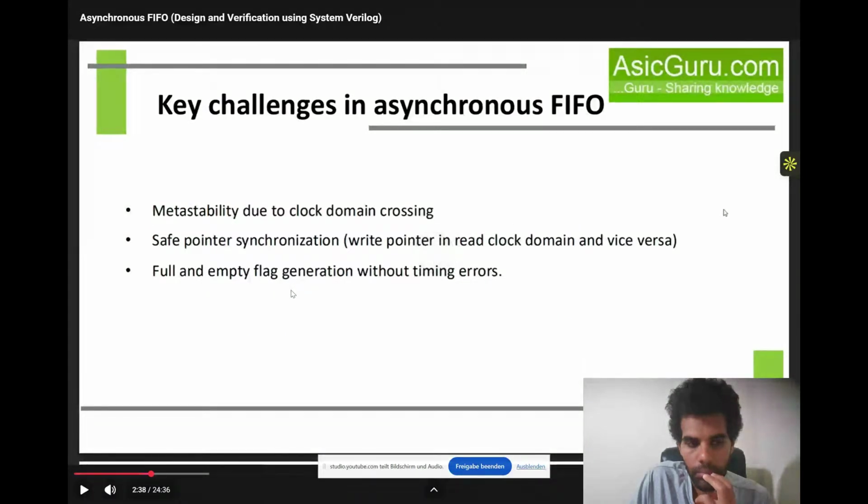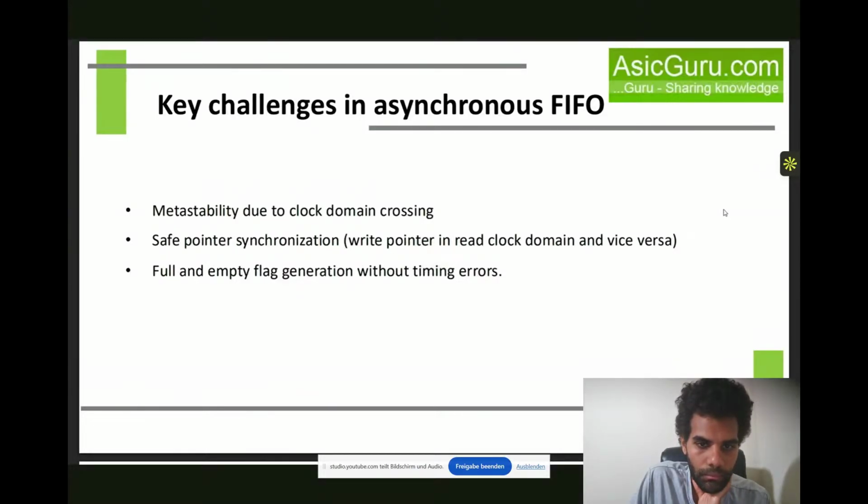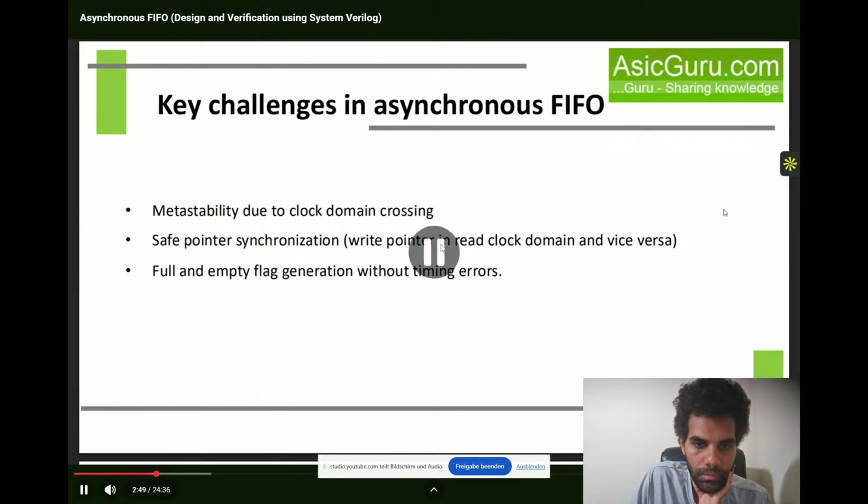Now what are the key challenges in the asynchronous FIFO? First is metastability, because data crosses clock domains. Second is pointer synchronization. Read and write pointers need to be updated safely.